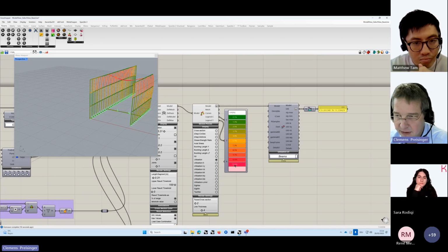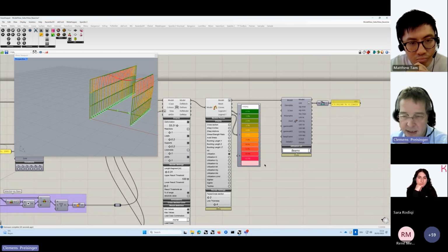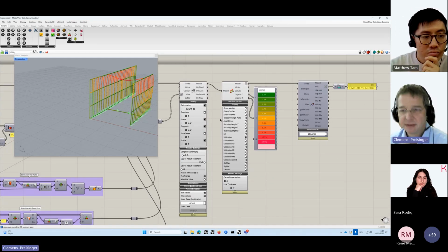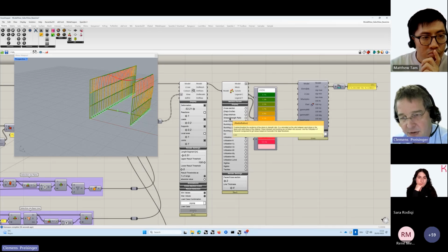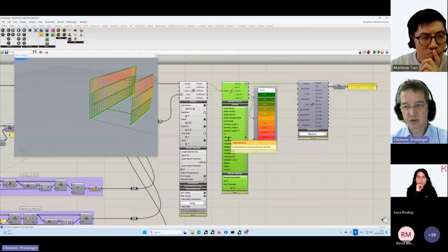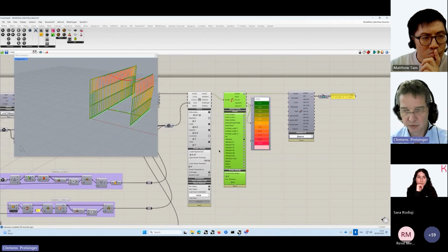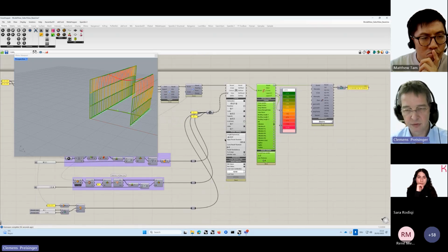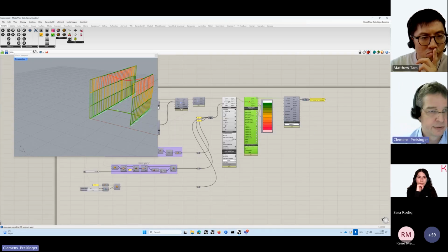You see here 12% corresponds to 0.12 at the utilization component. And by the way, this was sometimes a source of misunderstanding, because in previous versions Karamba also showed a utilization entry, but actually this was only the actual stress divided by the strength of the material, and the utilization is actually that utilization which is according to Eurocode, so including buckling length and complete cross-section design. So this is that.